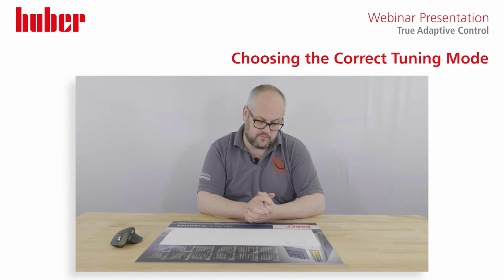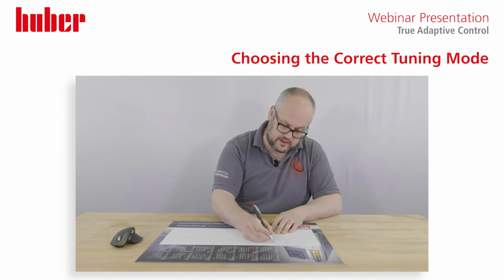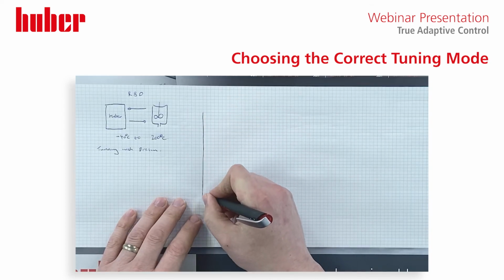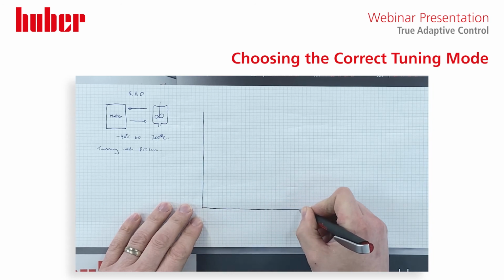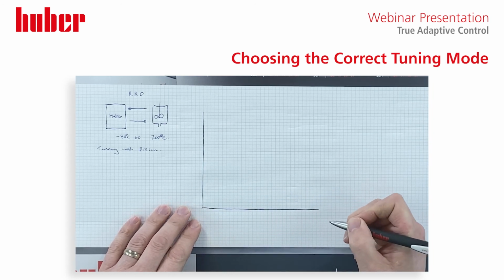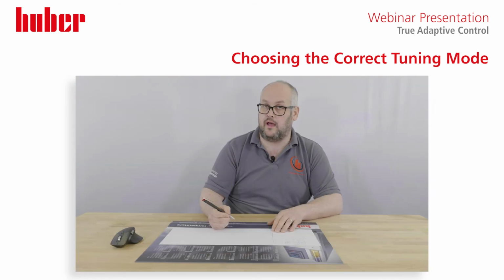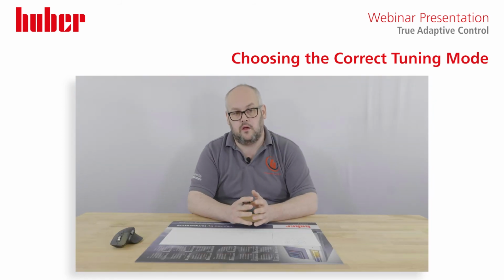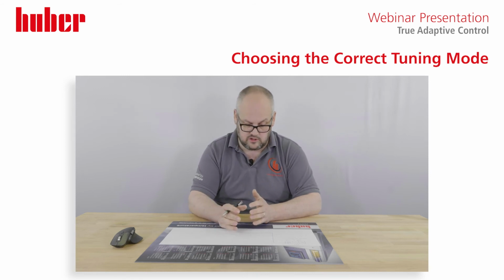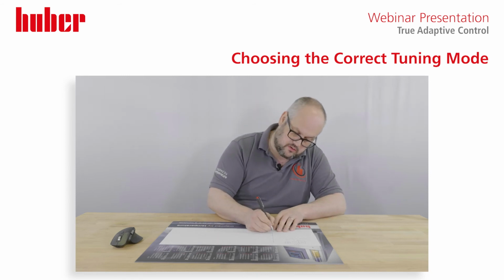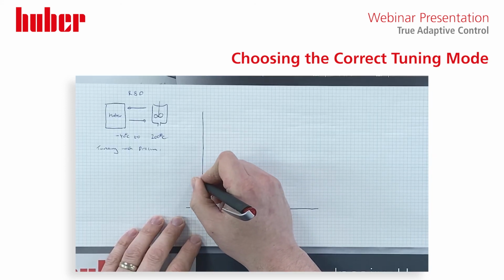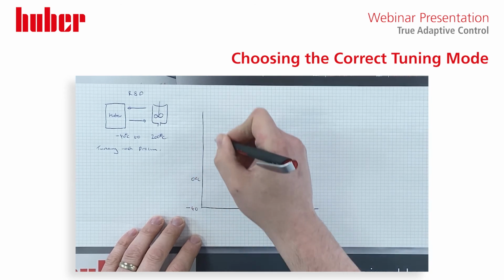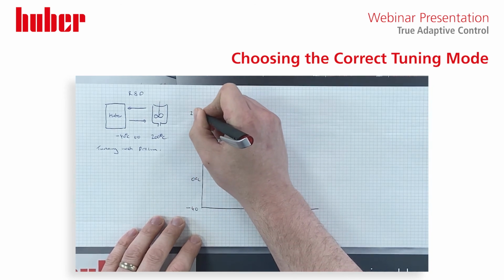Why do we do that? As stated, if we were to actually try PID tune from -40 to 200 degrees C, I won't lie, our unit won't like it because that's a very vast data range and the machine has a varying range of cooling powers across that range. So if we're to draw a graph here, with minus 40 being our starting point, 0 degrees C and 200 degrees C,